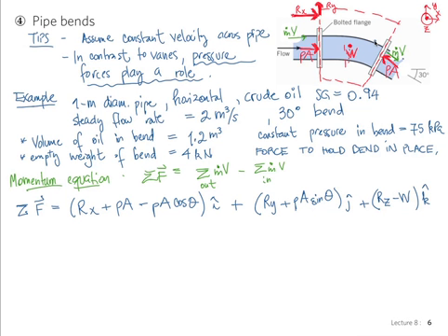So for that reason, the pressure in this case is the pressure exerted by the oil in the piece of pipe that we've cut out. And it's always going to be pushing into the control surface. Okay, so we've drawn all our forces, and we've got all of the components there.